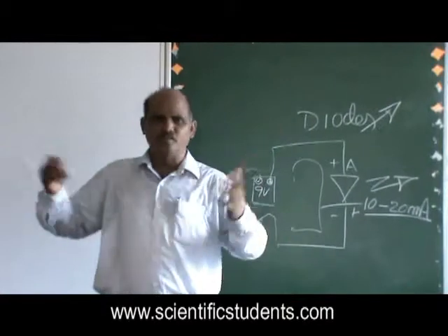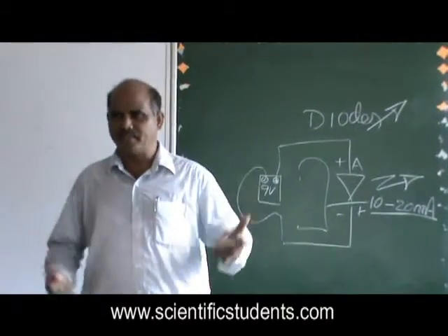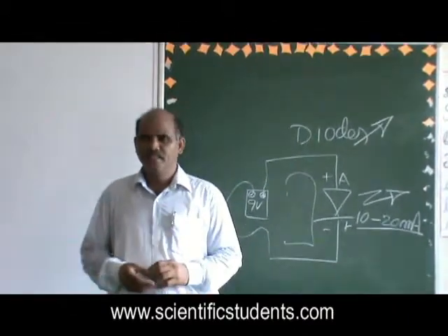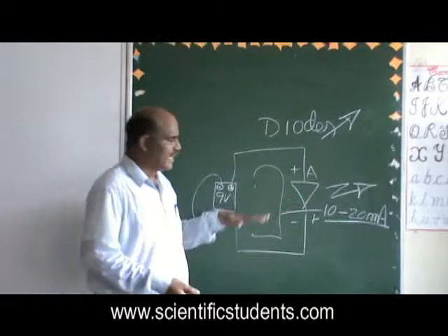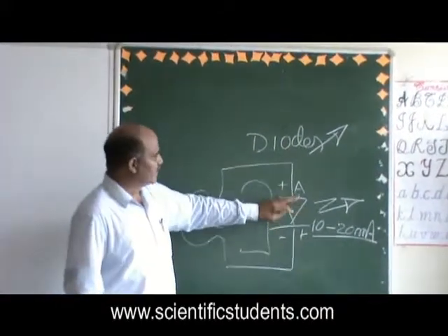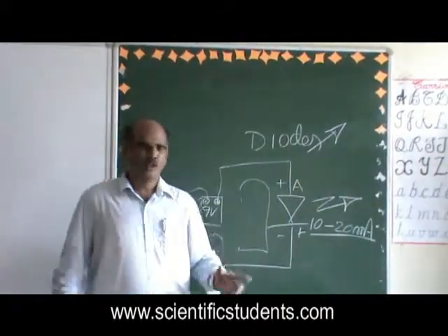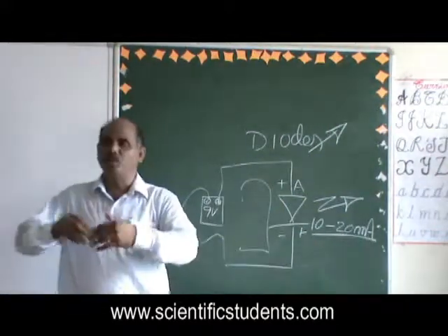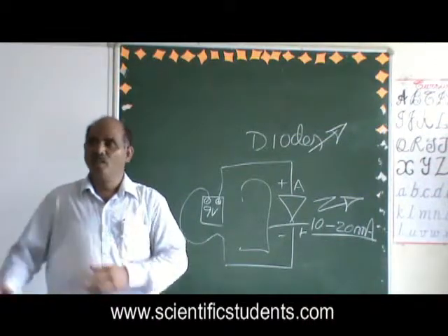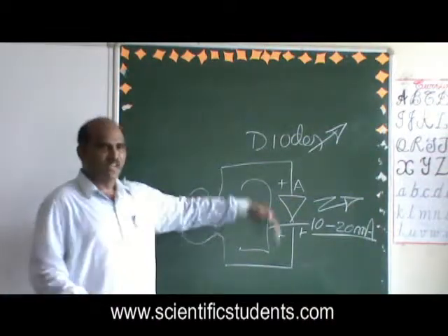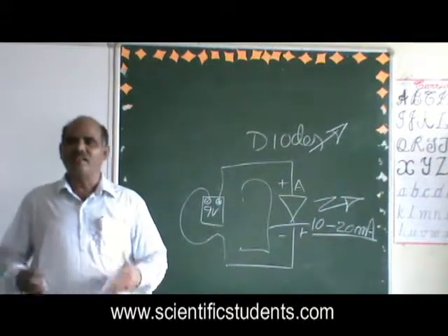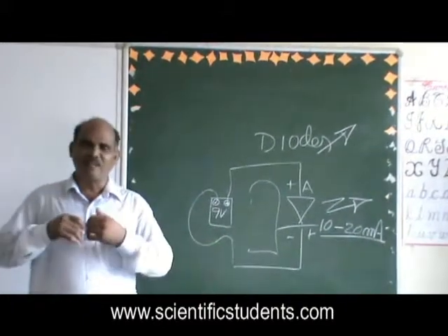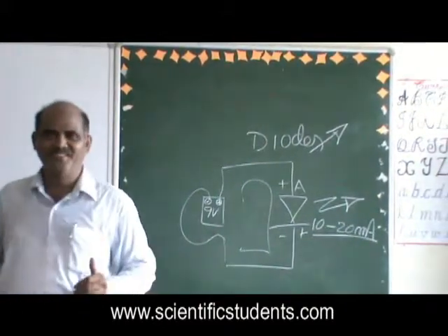Because of more brightness, more current, the junction got so much heated up inside, out of the rated capacity of the LED. Then what's happening? The junction is permanently getting open. After that it is an open circuit, it is no more connected. This is a semiconductor, when it is acting as a semiconductor, it is allowing a little current, and the result is light rays coming out. But when it is open, it is not allowing any more current to flow in the circuit. After that the LED is no more functional, no more working. It is permanently damaged, that he didn't know.